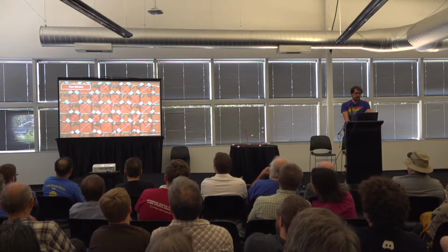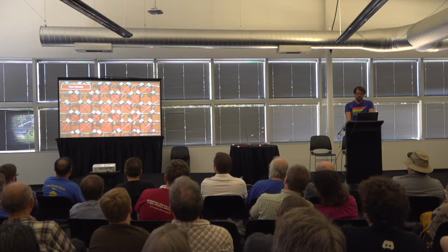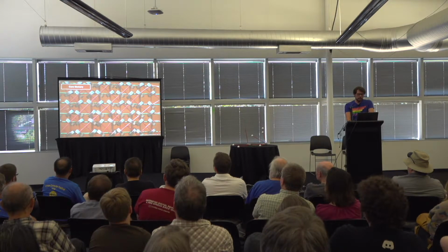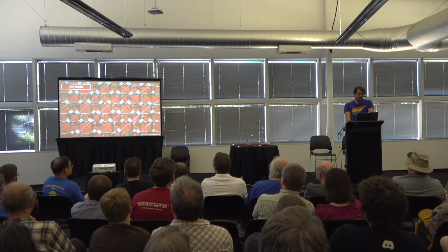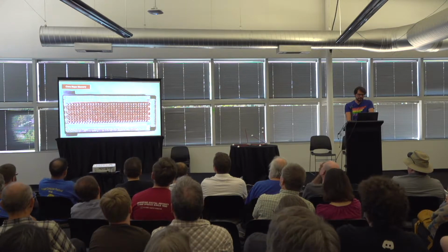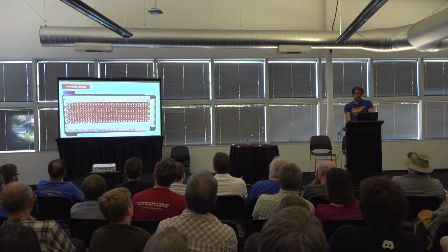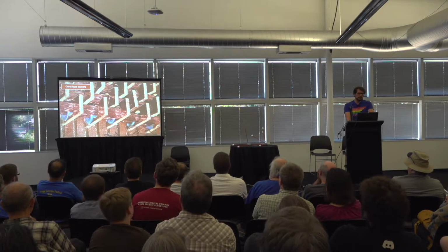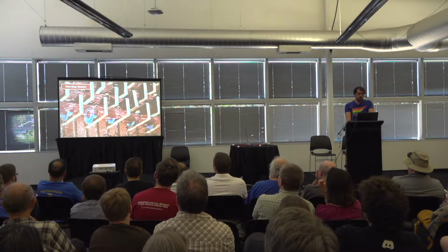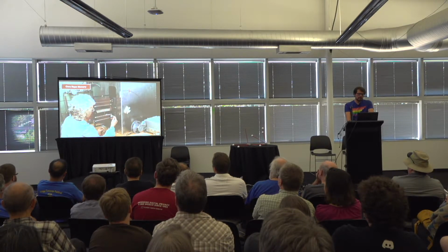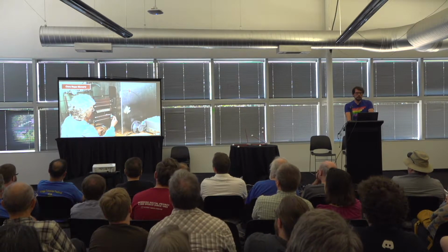RAM is implemented as magnetic core memory, which stores bits in magnetized toroids. Reading a bit clears it, so the memory sequencer makes sure to always write the value again after reading it. Without mass storage like tape, the AGC has an unusually high amount of ROM. Core rope memory encodes bits by wires that either go through or past a ferrite core. The 500,000 bits per computer were woven completely by hand.